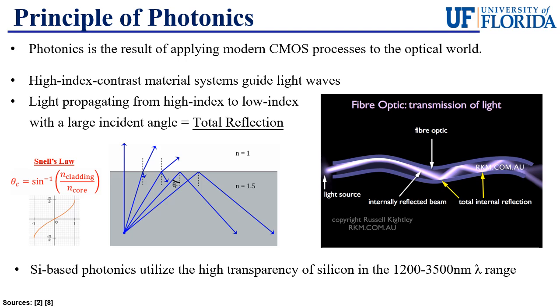Fiber optic cables will have a core that the light travels through that typically has a very high index of refraction. The cladding will have a comparatively low index of refraction and has the purpose of bouncing photons along the waveguide axis. Now, on the sine inverse function, a fraction with a lower value here will result in a smaller critical angle. The critical angle determines the minimum angle of reflection for a photon to totally reflect. Anything greater than that angle will reflect.